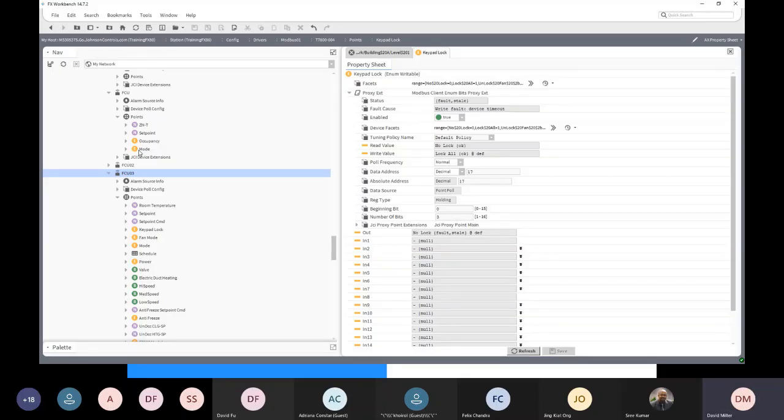Is it 50 power meters, all of the same brand, all of the same model? In which case, you've got one mapping table to decode and work out and solve and create, and then you copy it 49 times and your job's done.